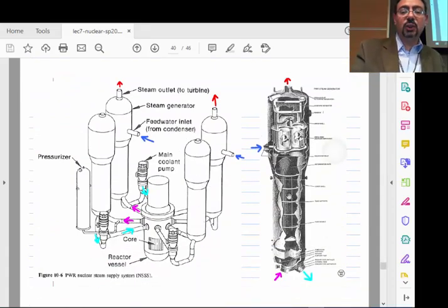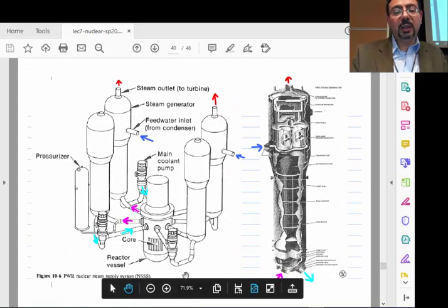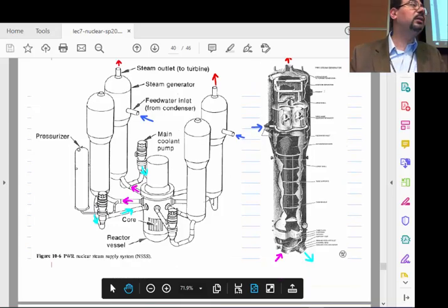And so here is a sketch of the pressurized water reactor. The core itself will have hot water leaving, cooled in this place, and coming back as liquid. Leave as liquid, come back as liquid. Leave as hot liquid, come back as cold liquid. And what happens on those things? Those are shell and tube heat exchangers.